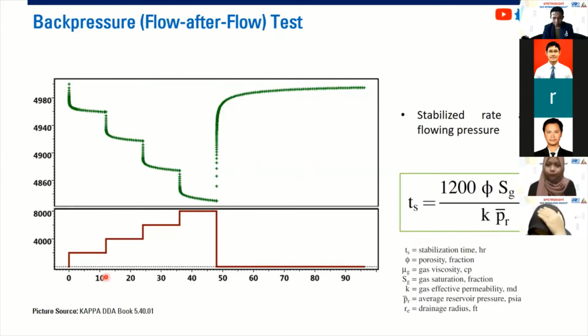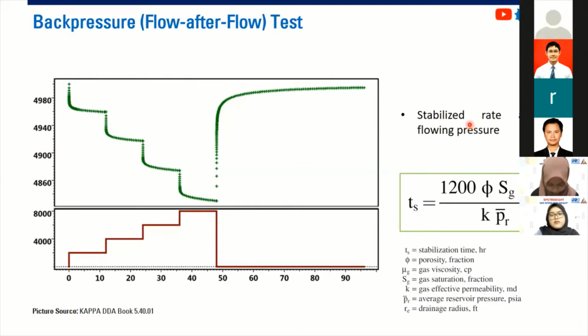and then increase the choke again. We have this Q2, again increase the choke, and then finally until the fourth data. You do this by the well testing, but the condition is this, the stabilized rate and stabilized flowing pressure has to be reached, which means that the well should approximate the pseudo steady state condition. We cannot do transient regime here. We need to achieve pseudo steady state regime.